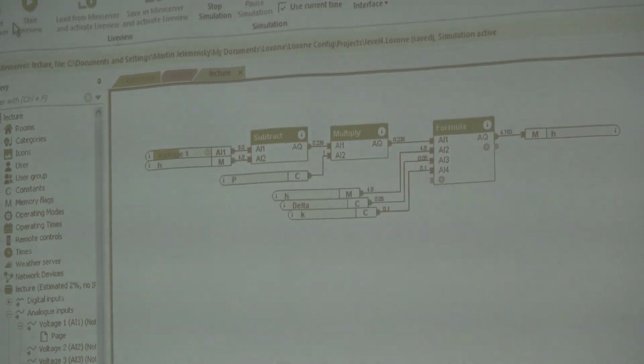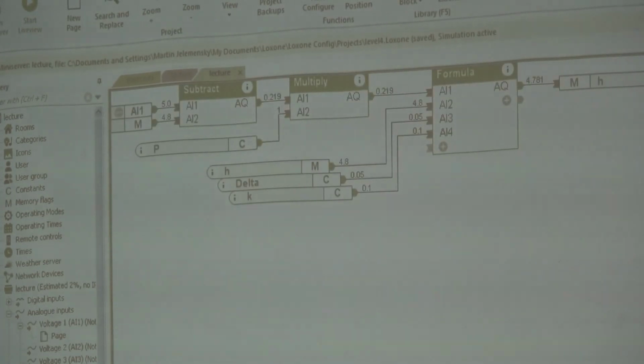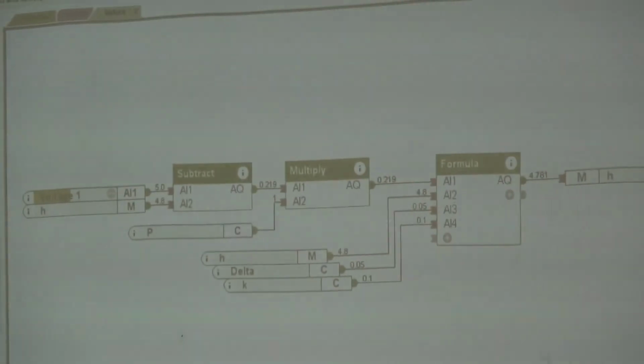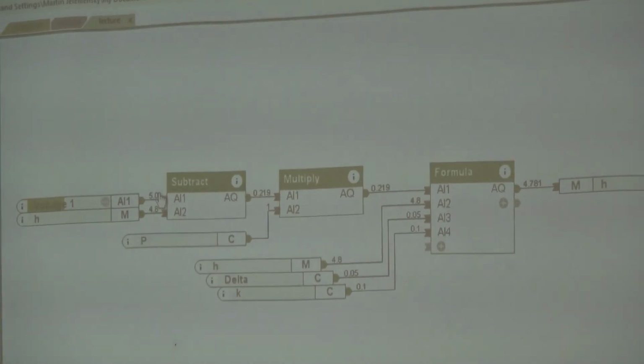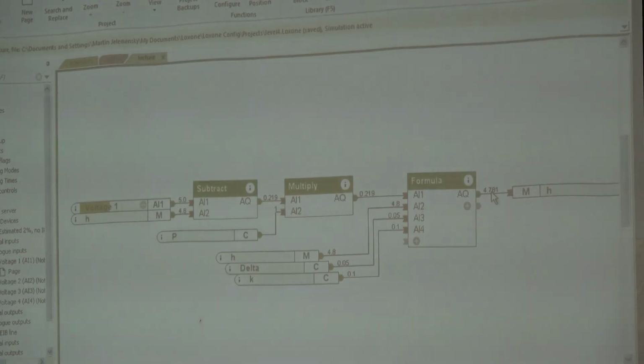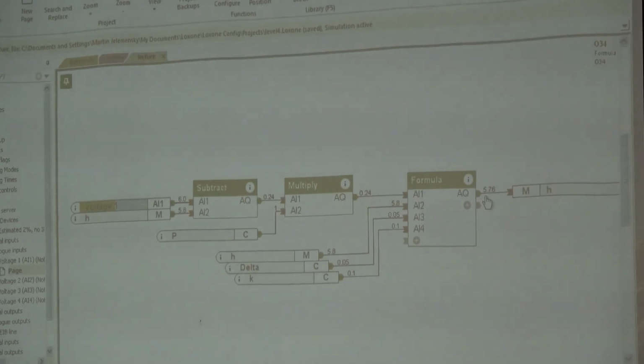Okay, let us zoom in. Currently the set point is 5, as indicated here, and we see that the regulated output exhibits some offset, which is of course not surprising, because we only use a proportional controller. We can get rid of the offset by using a PI controller, and that's what you will do in the exercises. Oh, okay, now it works. So you move the set point, it regulates somewhere else. So, okay, at least this thing has worked.